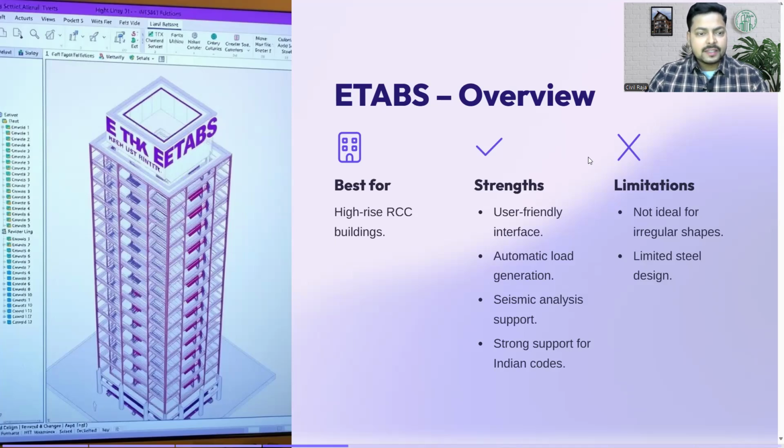Now, what are the strengths of Etabs? It has a user-friendly interface. Then automatic load generation is possible in Etabs. Obviously, it is also possible in STAAD Pro and Tekla Structural Designer as well, but it will count as a strength of Etabs. Then the third strength is seismic analysis support. It supports the seismic analysis.